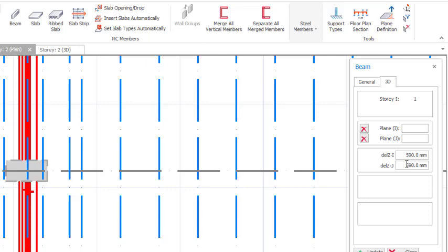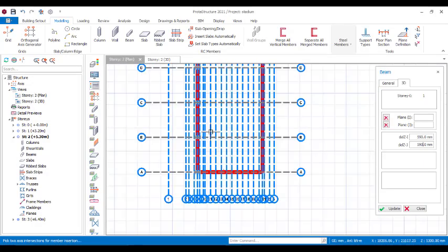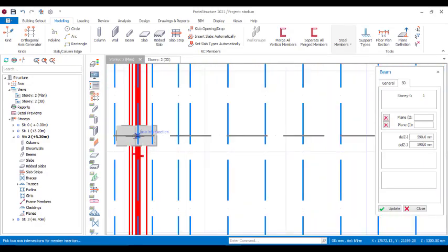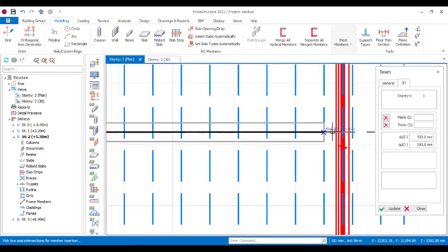When you draw a truss, the truss will go up. When you're talking about upstand beam and downstand beam, the truss is like an upstand. So I'm trying to draw this beam too as an upstand beam. Since the length is 610 and the truss is 600 mm, I want this one to go flush to the truss, so that will be like 590 upward, 600 minus 10. So I will just draw it from this point up to this point.